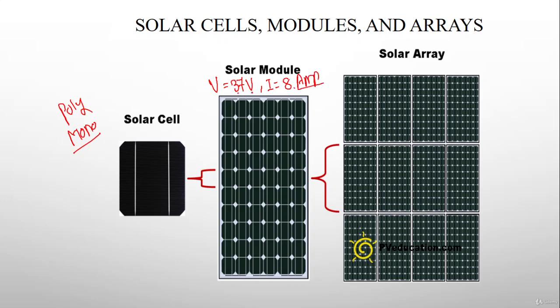This voltage and current depend upon the quality of the solar cell we are using, how many bus bars the corresponding solar cell has, and the total quantity connected in the series combination. According to that, the voltage and current change. In most cases, utility scale solar panels start with a wattage capacity from 250 watt peak up to 550 watt peak.